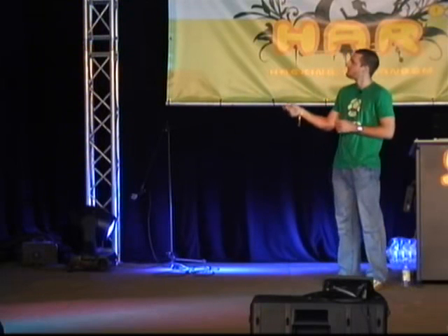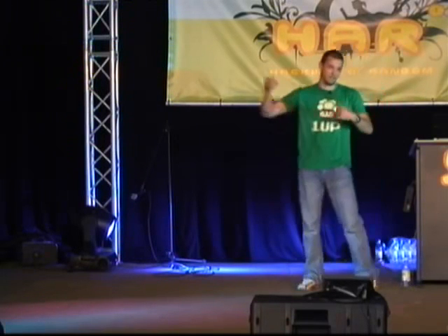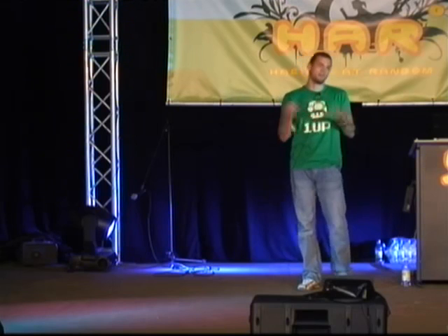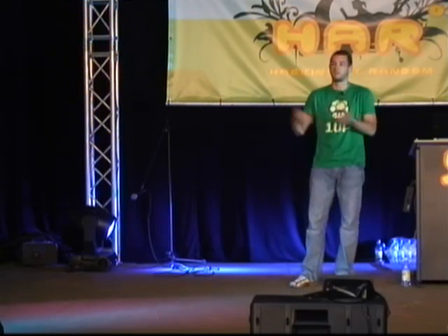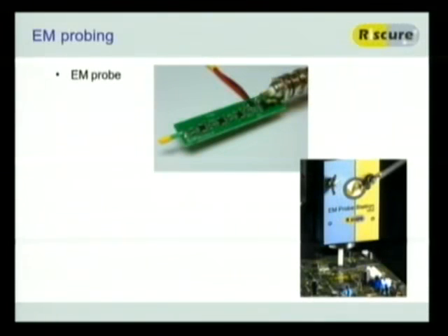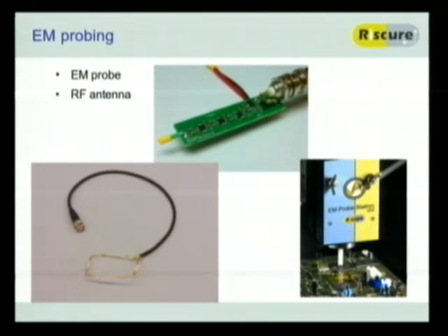What is hard to make is the amplification stages that we have behind it, because as you can imagine, the voltage differences over such a small coil are not very big. So we need to amplify the signal before we can actually measure it. This is what it looks like when you put some screws into it and hang it over a chip. When you have contactless cards, we built this high-end device.